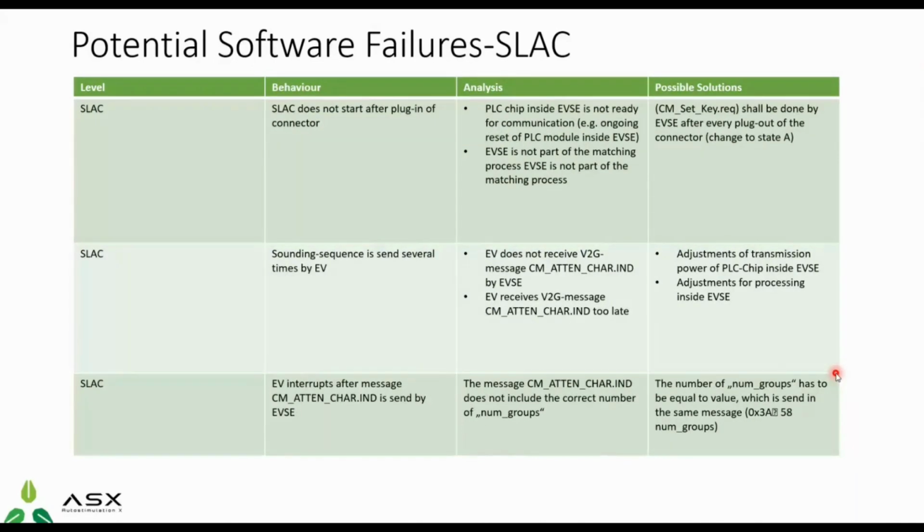Also, the second problem we have seen is that sounding sequences are sent several times for the PLC chip, because sometimes the power of the signal attenuation is also reduced. Then we found the EV interrupts after the message CM attenuation characteristic, which is sent by the EVSE. So these are the messages, and this is a deeper view going into SLAC.